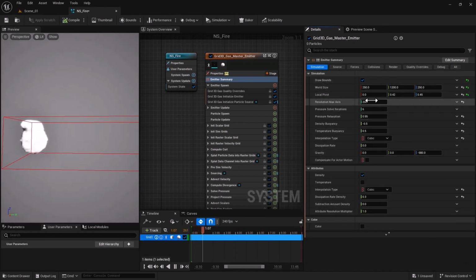All right, let's deal with the direction of our smoke, and then we can move on to the next chapter and put final touches into the Niagara system. One thing you should be mindful of is never rely on this display 110%. Sometimes you bring this smoke into your scene and you see a slightly different result. So it would be a good idea to drag and drop your Niagara system early on and always sanity check when you think the result works for you.